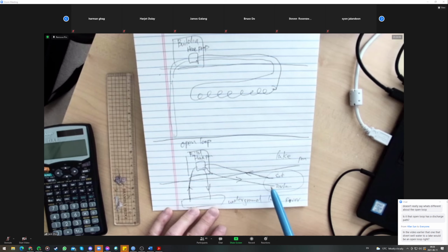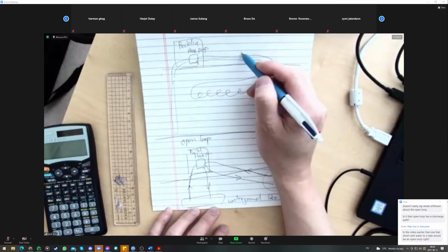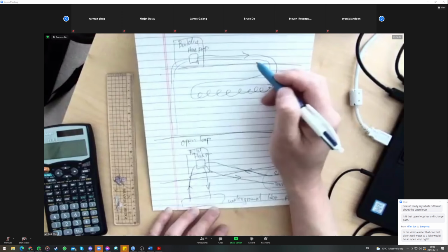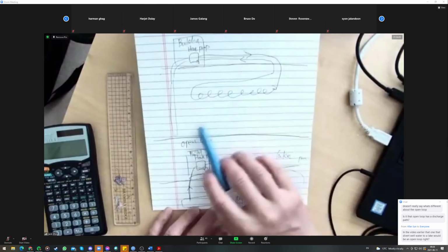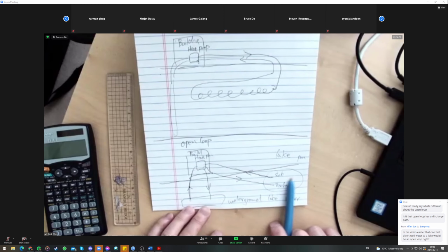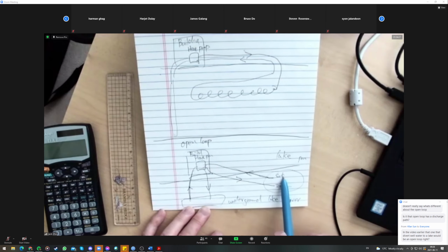So as long as your piping is not complete. Because with the closed loop, you have a complete piping system for the water or anti-freeze solution to circulate down there. You're not exchanging anything with the outside. But here, you are changing the water. With an open loop, you only use water. You take in the water from one place and release the water back.